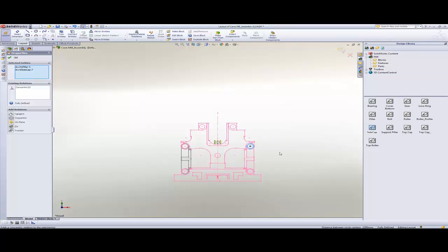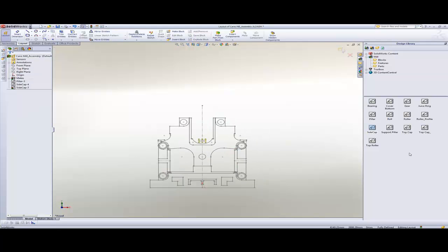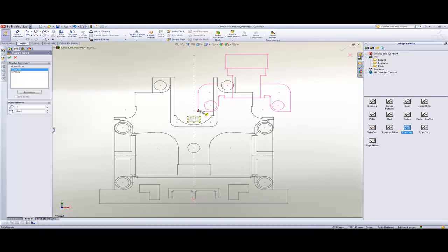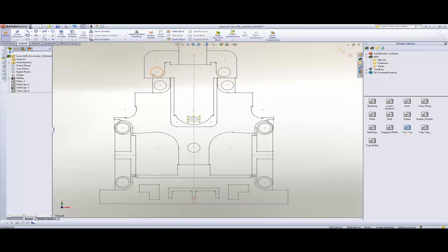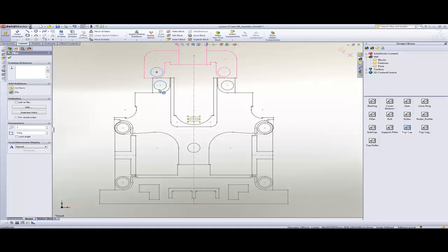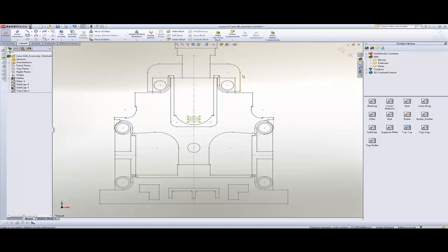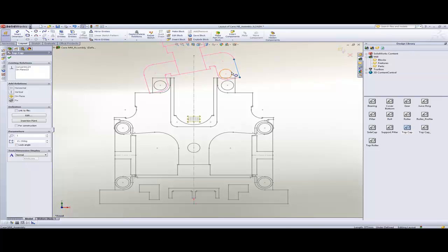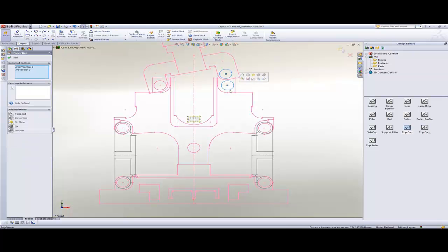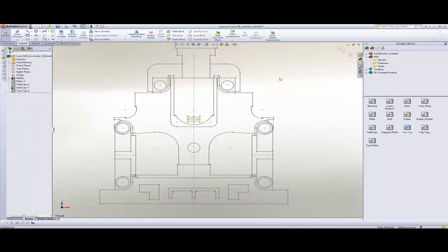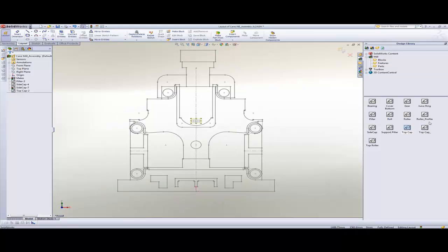We have already called in the pillar and the side caps. Next, we would need to have a top cap and few other rollers. 3 key rollers will be in triangular formation to crush the cane, which are driven by gears on their shaft. Fourth one would be a feed roller driven by motion of others.